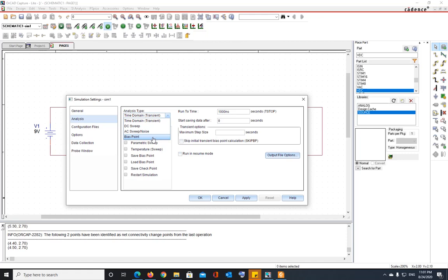If someone is learning how to put together a circuit and where to connect meters to observe voltage, current, power, stuff like that, then the best software is Multisim, because you virtually put your meters in Multisim, and the same thing you can do hands-on on the bench. But for PSpice, you don't really have to put meters. All you have to do is to click on the meter, and the values will be printed right on the circuit, as you will see very soon.